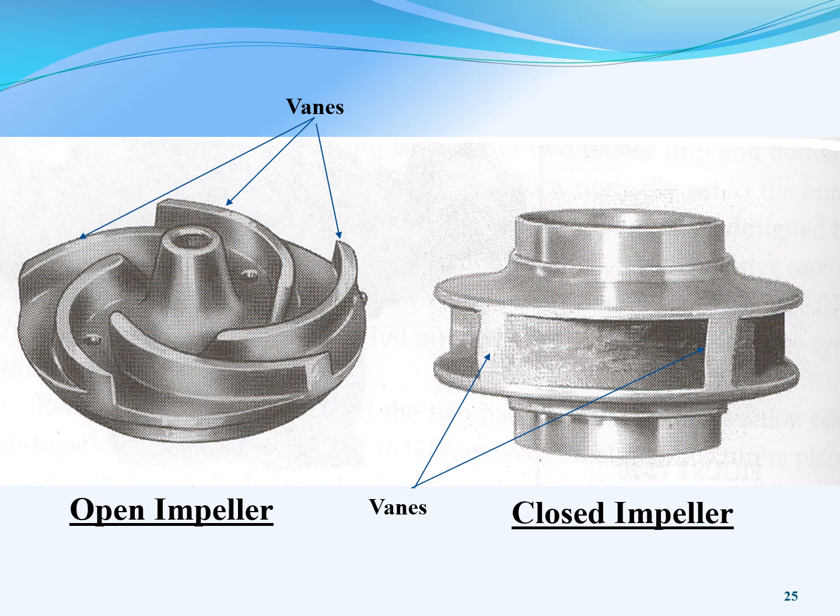So in this case here, we've got an open impeller, right? You can see how solids are able to move through here and be discharged, whereas with a closed impeller, you don't have that option, right? The closed impeller would not be suitable for solids. But again, if you're trying to achieve high efficiencies, it's definitely the better impeller option.